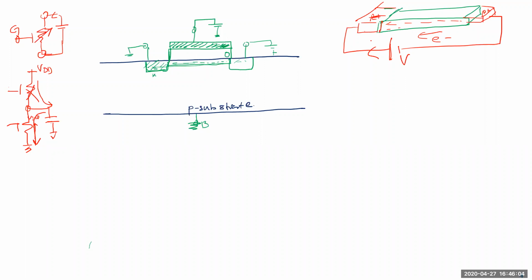Right. Okay, so the next question was, what happens if I replace this metal with a P plus semiconductor? Then it won't conduct. And why not? So the substrate is also P-type. No, forget the substrate. Now I'm giving you an isolated problem. You have a channel with this charge, which is just electrons. Just assume that this is a gas of electrons. Actually, here the source is at reverse bias, so it's difficult for electrons to flow from the source to that channel.